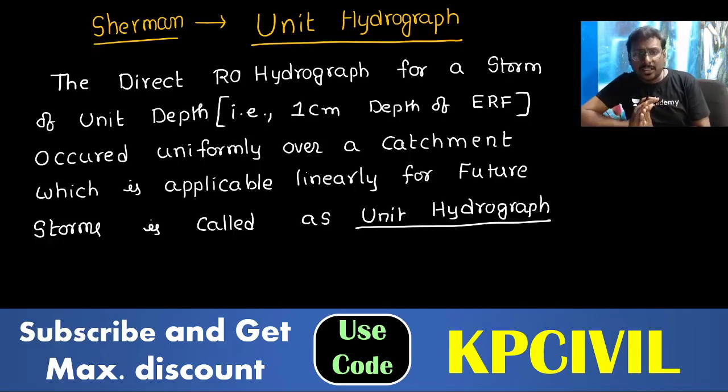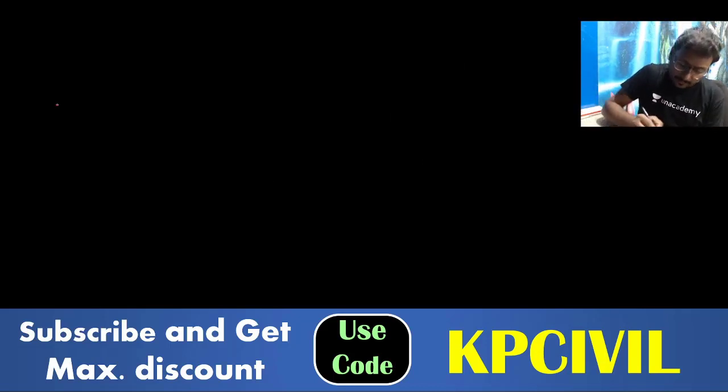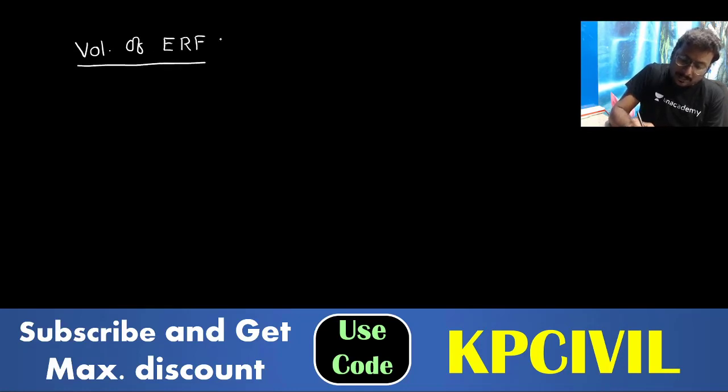So I will make the concept of unit hydrograph very simplified for you. When you consider the volume of effective rainfall entered into the catchment, this is taken as the area of DRH, which is equal to area of catchment into ERF depth.